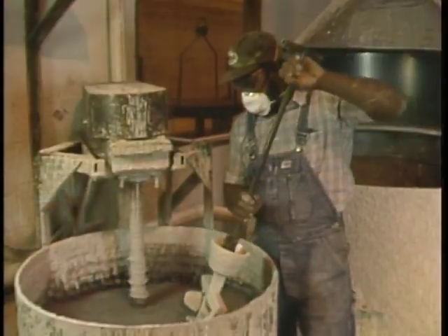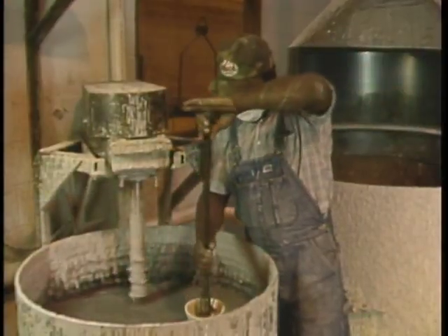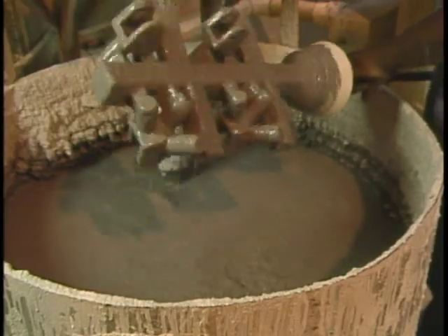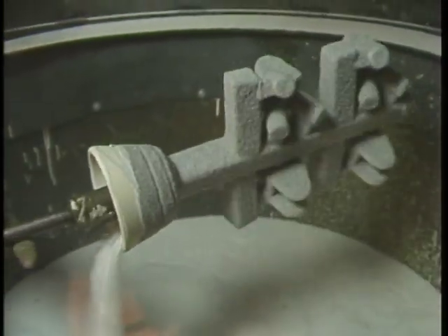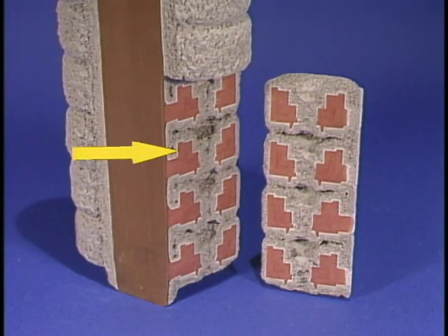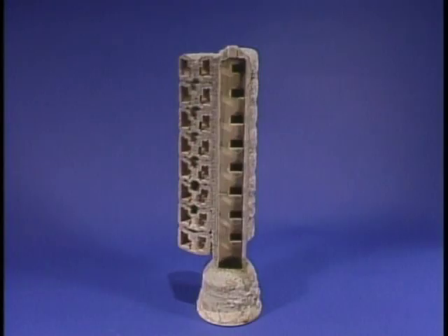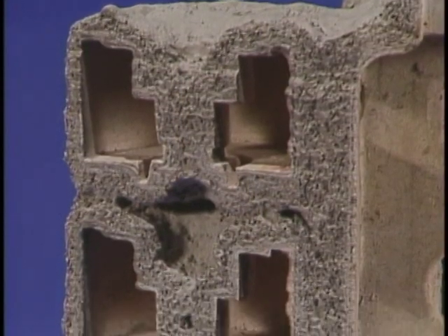Such equipment is programmed to follow the normal hand dipping procedures, to reduce labor costs, and to remove variables of a manual operation. If we take a typical assembly and section it, we can see how the ceramic coating faithfully follows the contours of the wax patterns. And when the wax is melted out, a precise cavity remains into which metal may be poured.